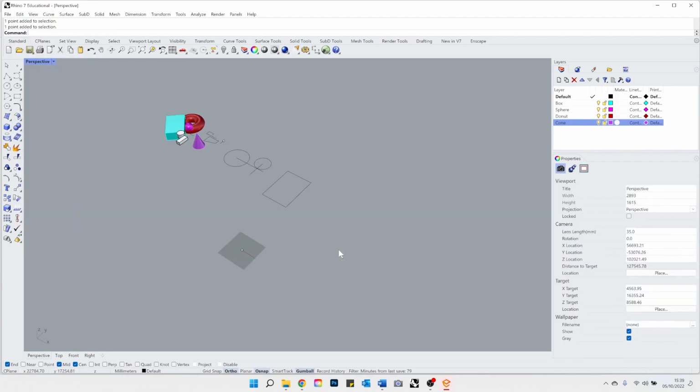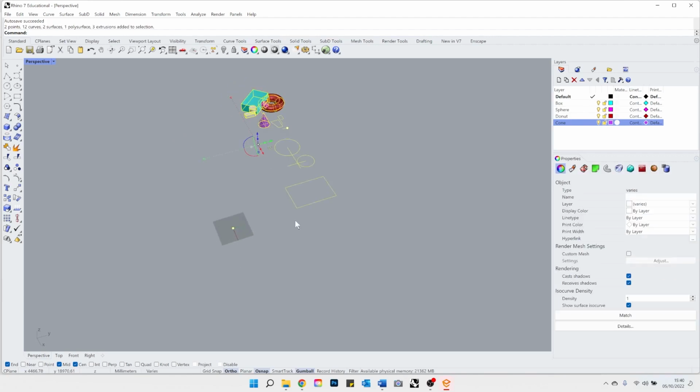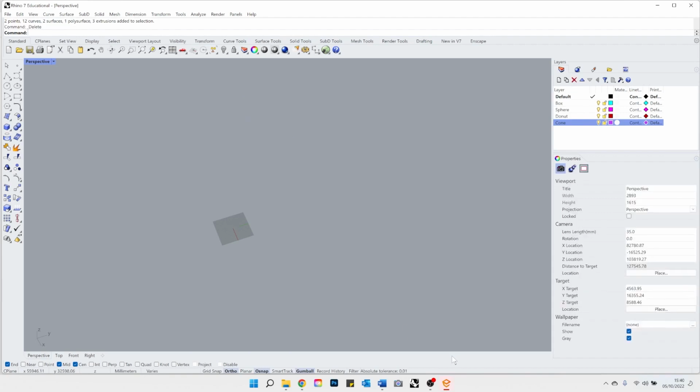Before we start moving into something a little bit more architectural, I'm gonna quickly mention all the different methods of 3D modeling in Rhino, which is a key principle, so the key information that you need to know about Rhino. So if you still have the same canvas that you were working on before, if you're not too emotionally attached to it, do Ctrl-A and delete it. Ctrl-A will select everything that you currently have on your screen, and just click delete to have a nice clean empty canvas.